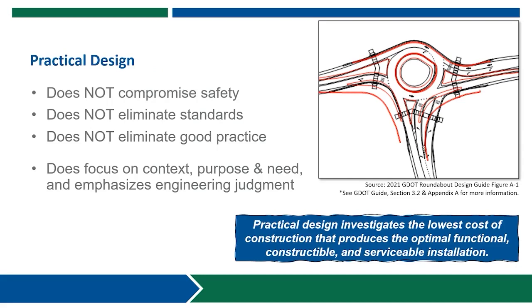Another important high-level concept is practical design. Designers should be looking to optimize the circle size, location, and alignment of legs to promote balanced speed control on every approach and ensure efficient movements. It's essentially design optimization with a greater emphasis on balancing cost with capacity and safety benefits, and this requires careful consideration of design trade-offs.